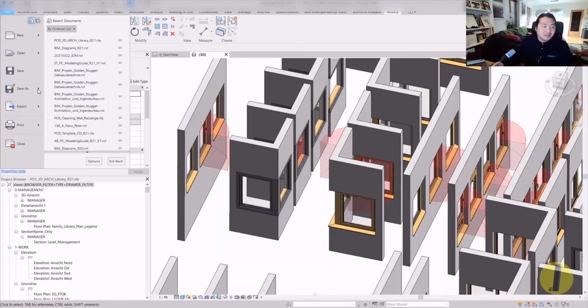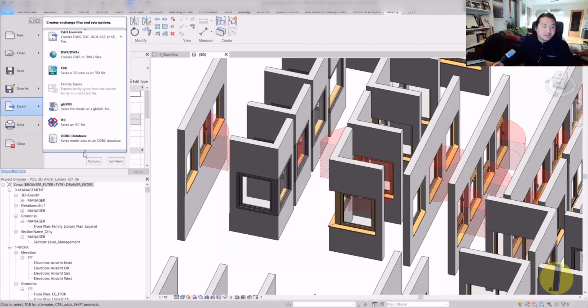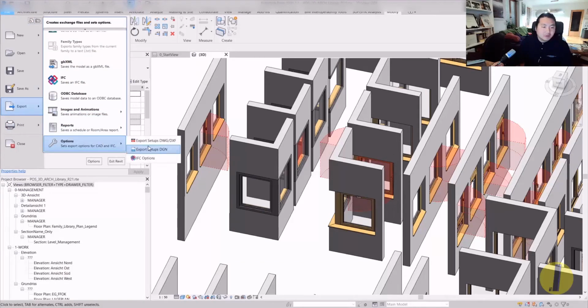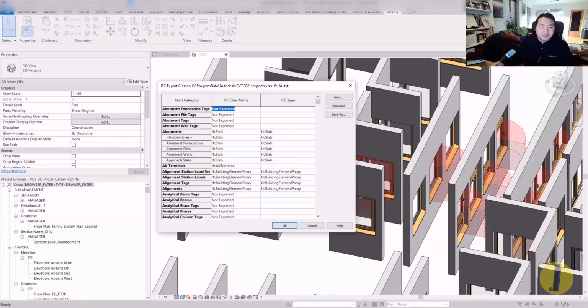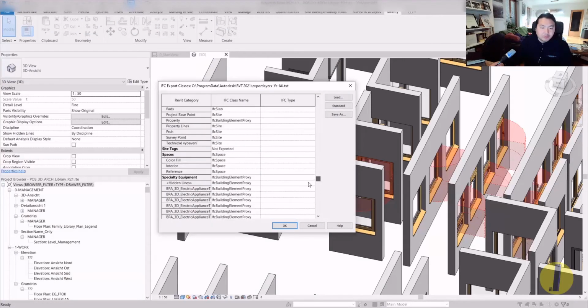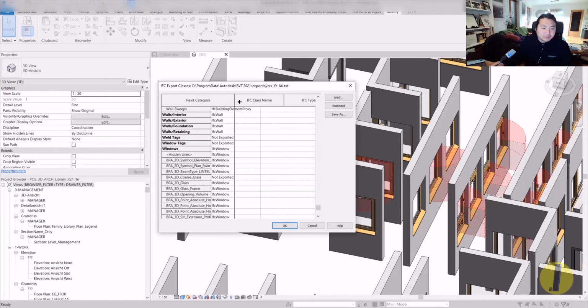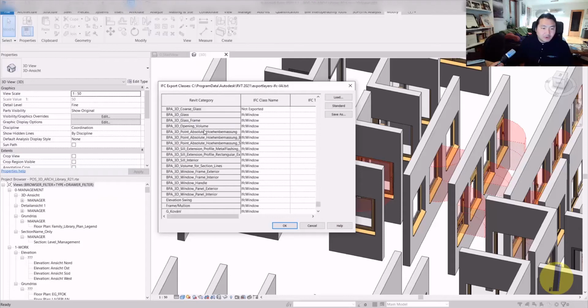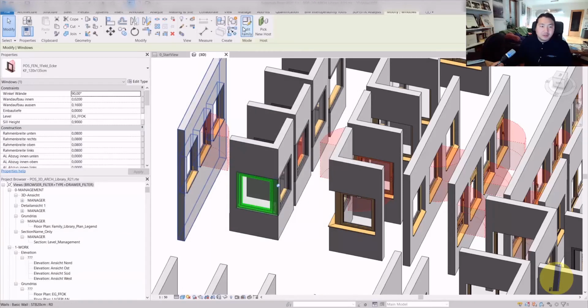So of course in Revit you can go to export mapping. When you go to export mapping here, you can control from door or window. Let me go to window. This coarse fill view, let's say coarse, you can map to not exported, but even though when I say it's not exported, it still exports this geometry, which I'm not sure why it happens, but which is annoying.